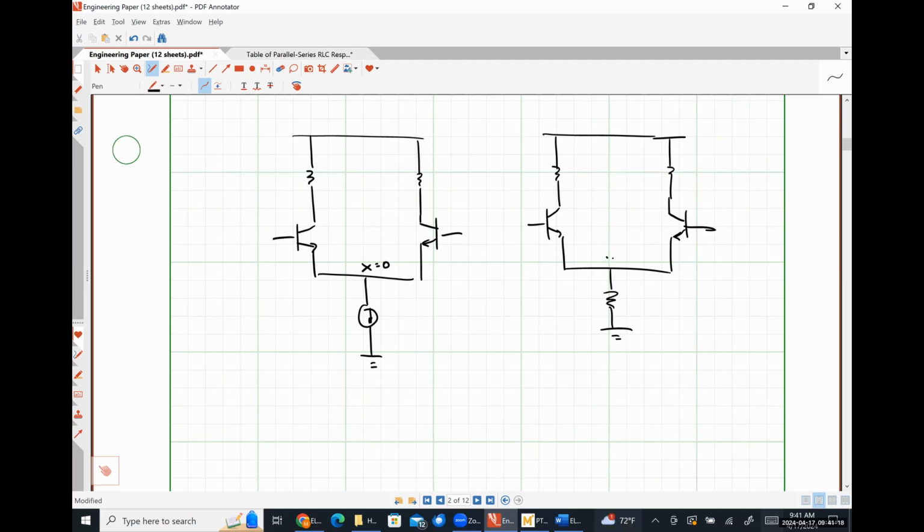The circuit is symmetrical, so that voltage there is still literally going to be equal to 0. So it's not going to impact your differential mode gain literally at all. This resistance right here, which would just be R0 of whatever transistor that is, only shows up when you're doing your common mode gain calculations, because those depend on the tail resistance. That's literally it.